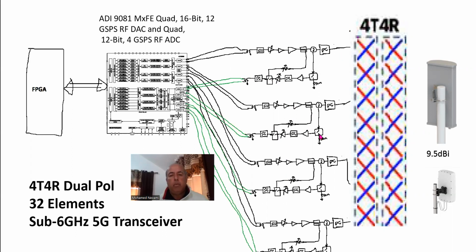You can go back to my video and watch the details of this. But all we need to make up a 5G mmWave transceiver out of this is to get rid of the high power section in here, keep this section, the LNA. We're also going to eliminate this. This was the path where you take the PA and route it to the receive path to do linearization and power control and other compensation, or to check your transmitter spectrum, just to validate the system, the transmit path.